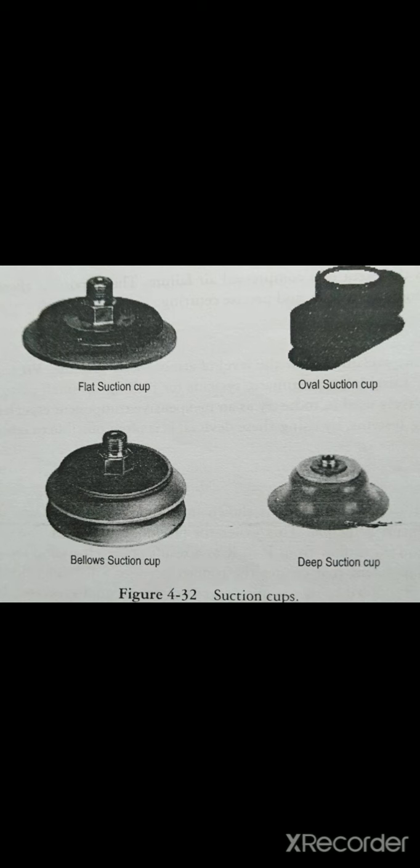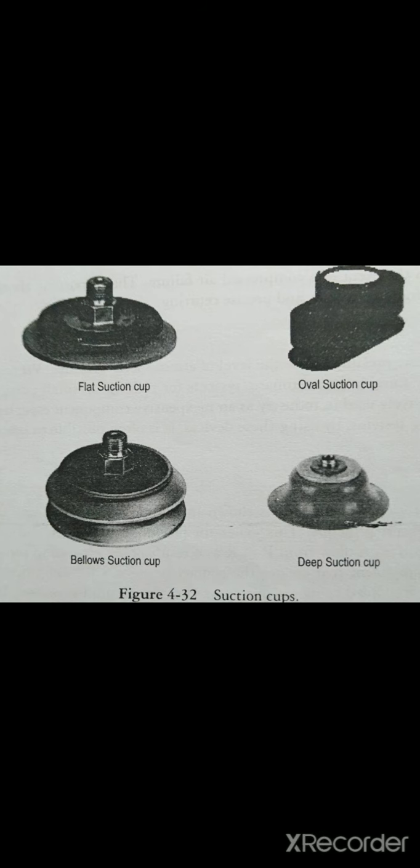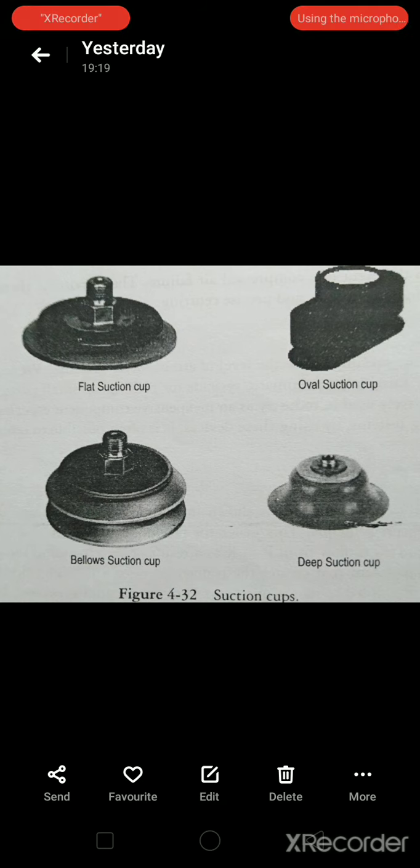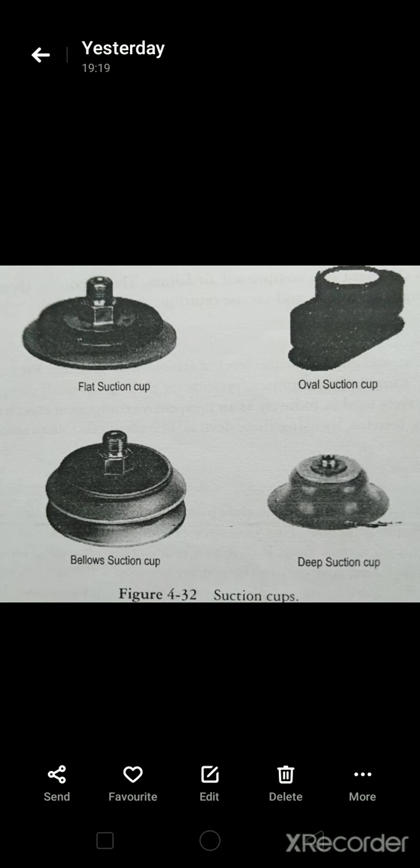The suction cups can be used to pick up and grip workpieces with smooth and non-porous surfaces by vacuum. When vacuum is present within the suction cup, the workpiece is pressed to the cup by atmospheric pressure. The soft suction cup makes certain that the surface of the workpiece is not damaged. Bellows suction cups can pick up workpieces with a slightly uneven or curved surface. Suction cups can also be used to grip non-magnetic materials such as glass, ceramics, and wood.